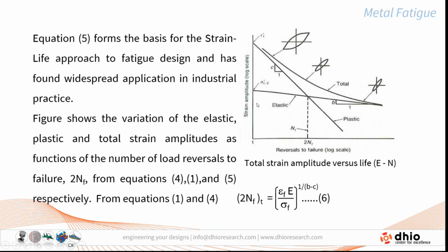Here we can observe that in the region with the number of cycles less than NF, that is, at the intersection of the elastic behavior and the plastic behavior, the plastic strain is mainly causing the fatigue failure.